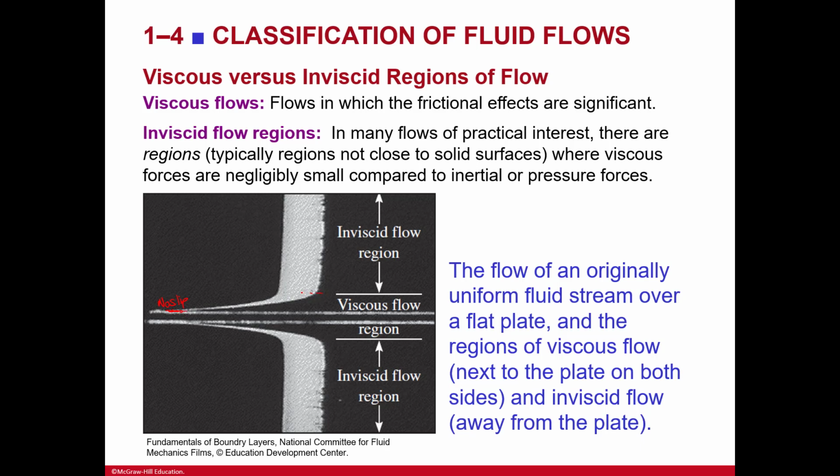But viscous flow really encapsulates not just the no slip, but really where that flow is just not where it should be because of the boundary layer, because of the no slip condition, because of the viscous effects. So this is the viscous flow. And then when you have separated and you're no longer experiencing the friction caused by the surface, that's when you're going to get into a normal flow, and that's the inviscid flow region.